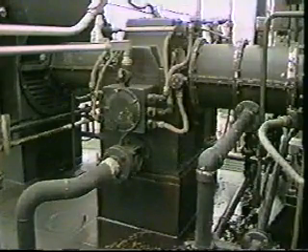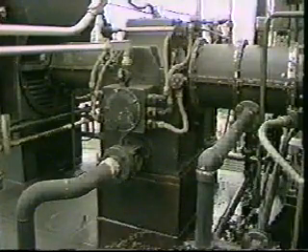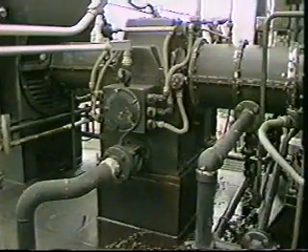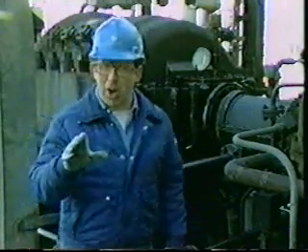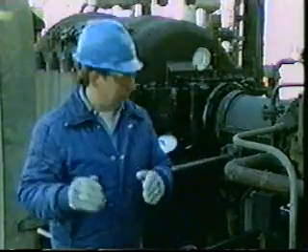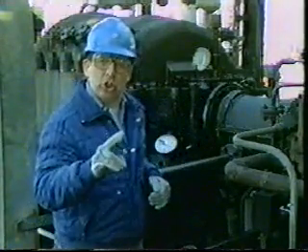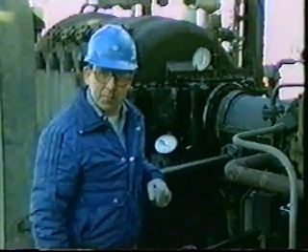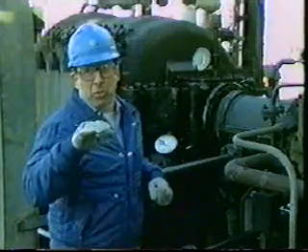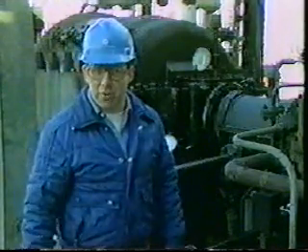Gearboxes can either be an integral part of compressor construction, or they can be external auxiliary equipment connected between the driver and the compressor. Almost all compressor driver applications use some sort of coupling. Couplings are used to transmit motion between two shafts that are almost but not quite in perfect alignment. They must also be able to withstand changes in compressor load or stoppage of the driver altogether.